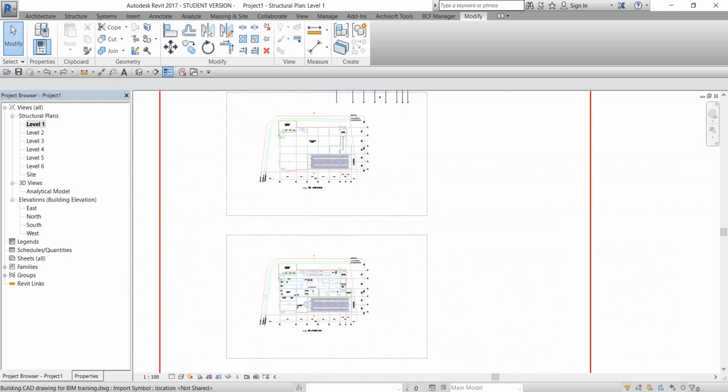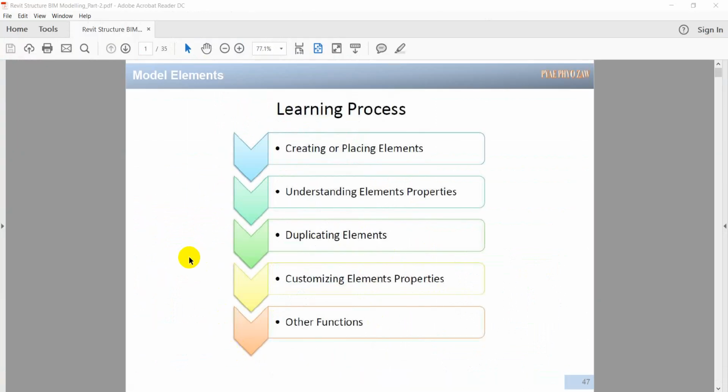So the best thing is, if you have the CAD file, you do not draw all the plans in one CAD file and link it. A lot of people think it is very difficult to control. You better separate all the files. Let's say the AutoCAD file has the file for each level, you separate the files, then you link each to each view. Then it's easy to control.